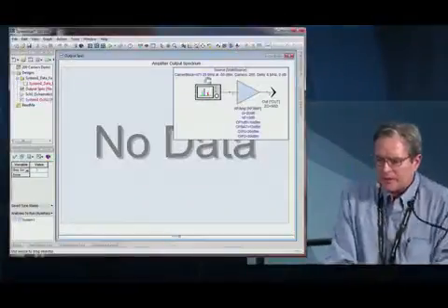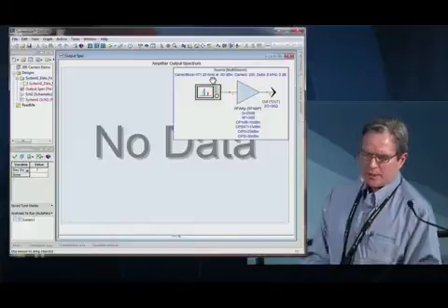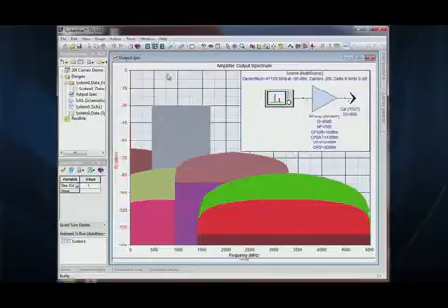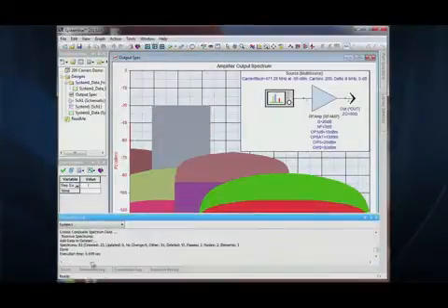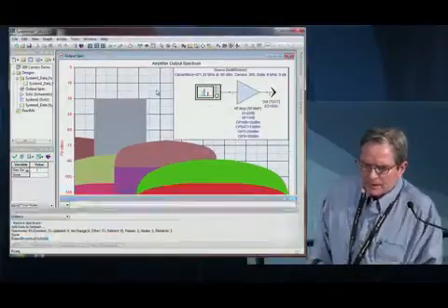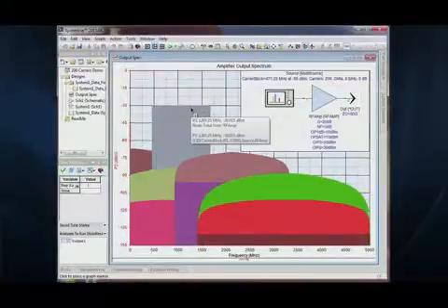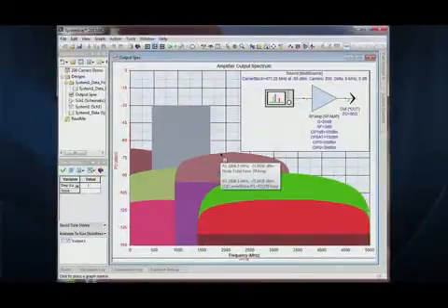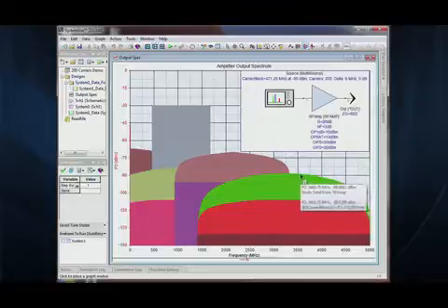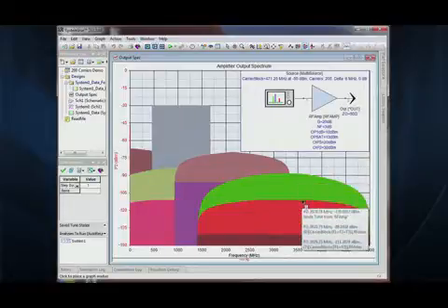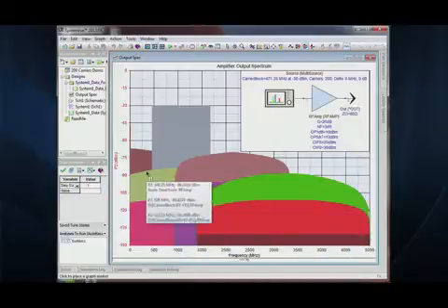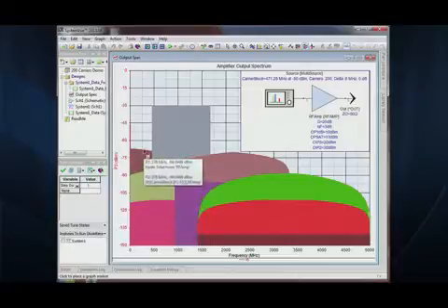All right, and here's a little video, and this is all real time. What we're going to do is simulate a UHF block. This is 200 carriers, simulated in real time. And so you see the intermods out to about 3 gigahertz. As you mouse over this, you'll see the carrier block. And then we're going to go down and look at the 1+1 intermods. This is now the second harmonic. This is the composite triple beat, the sum products. This is the 2+1s, and there's the composite triple beat underneath the carrier.